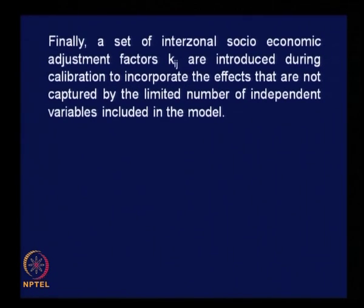And finally, a set of interzonal socio-economic adjustment factors given by the notation small kij, lower case kij, are introduced during calibration to incorporate the effects that are not captured by the limited number of independent variables included in the model. We have just 3 independent variables in this model.